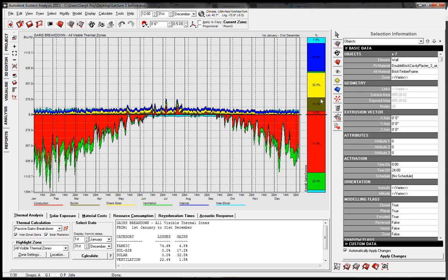And a lot of the solar gain now happens because of direct solar gain. Let's not worry about the direct solar gain because that's just sunlight falling on the building. But you realize the overall area in our heat gain has significantly dropped. Now our heat gain area is given as BTU per square feet, which is British Thermal Unit per square feet of area. So we've really reduced the heat gain of the building by changing the color.